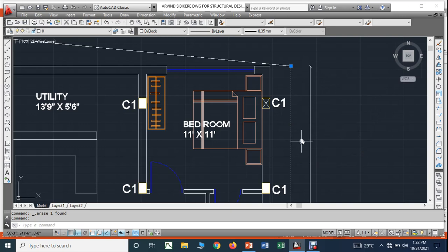Therefore, maximum of half a foot or 1 foot there will be a gap between the two external walls of the building, which leads to poor circulation. You can see in many metropolitan cities, in order to save money, without any setback they will construct between the two buildings. Therefore, when you go to the top floors or the bottom floors, you never get any kind of circulation. It will always be damp.